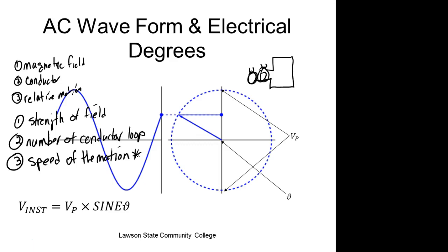And that's what the regulator in your car does. So if you're sitting there mashing the gas and your lights are getting bright and dim, it means you're having problems with your regulator, right? You understand that? So you can go out there, roll your windows down, turn on your lights, have your air conditioner running. If you put a meter out there, it's going to measure right around 14 volts. It's not going to be perfect, it's going to drop a little bit, but it's not going to drop much.